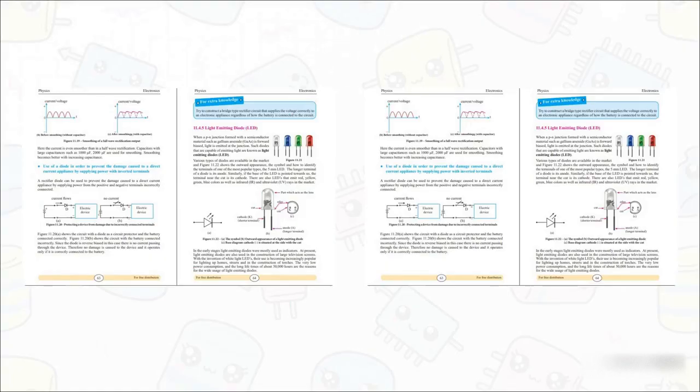So cool. So now we've got a current that's always positive, which is great, but look at it, it's still super bumpy. It's not a smooth ride at all. So we add one more simple part, a capacitor. You can think of it like a tiny, super fast battery. It charges up on those peaks and then releases that energy to fill in the valleys. And just like that, we get the clean, smooth DC power that all our electronics need to live.